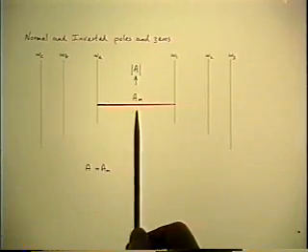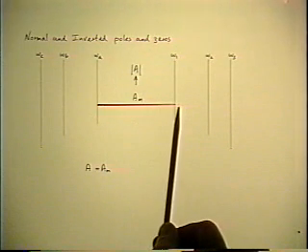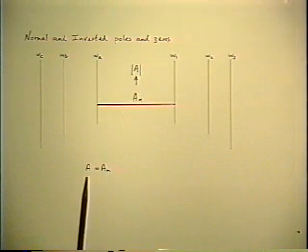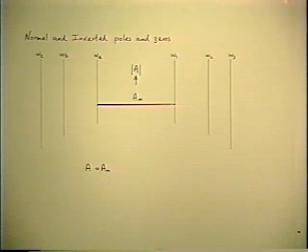Given the sketch, which locates the corner frequencies, which is the specification you have to build, that's the starting point, remember, the answer to the analysis. Given the sketch, the first thing to do is to write down the corresponding algebraic expression in factored pole zero form, which is the reverse direction. So, starting with this picture, this is the flat gain. The expression that goes with it is simply A equals AM.